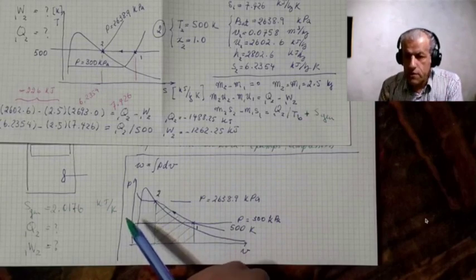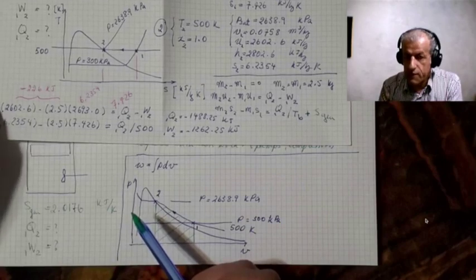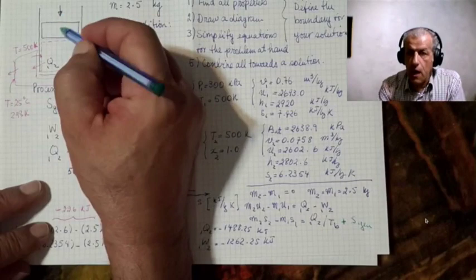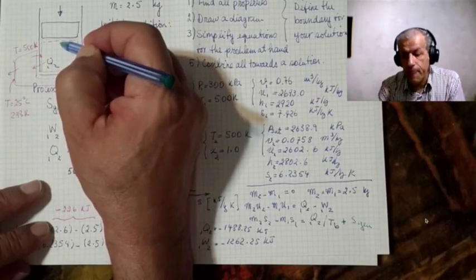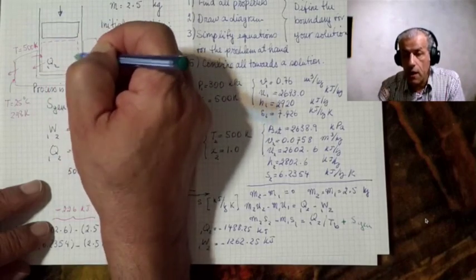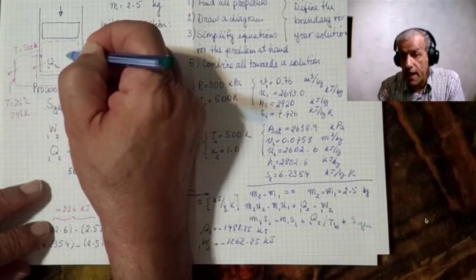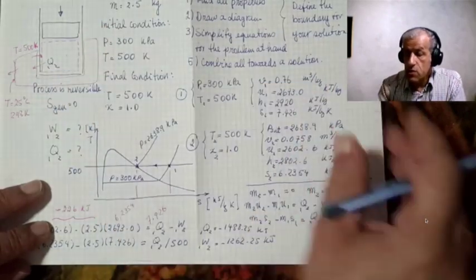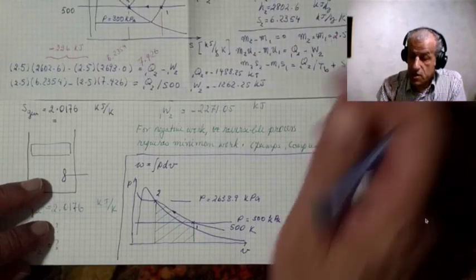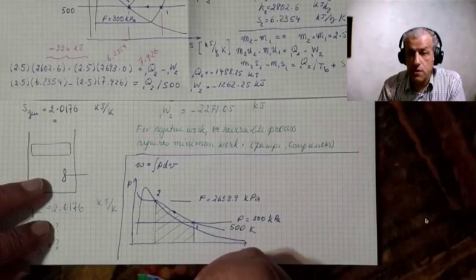There is a point in this problem which we have to note. Since work is done on the cylinder, on the piston, and the work is done on this vapor, therefore the pressure inside should be accounted for. We have to use pressure inside the cylinder in this equation.